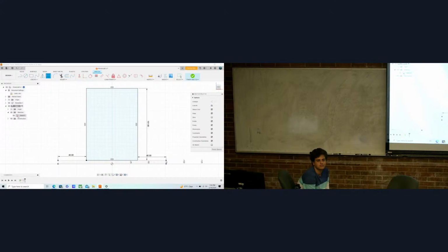So if you delete that dimension and drag it in, then it will dimension appropriately instead. Okay, so you just control Z because you have the dimension. Yep, and then you can drag that line, the blue line. And then you dimension it, because that way it's this side, not that way.